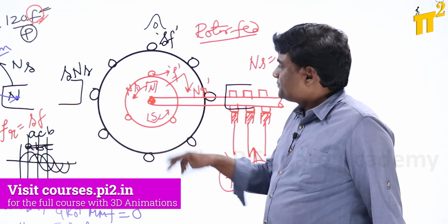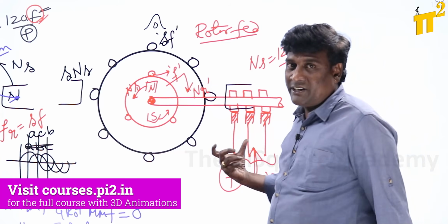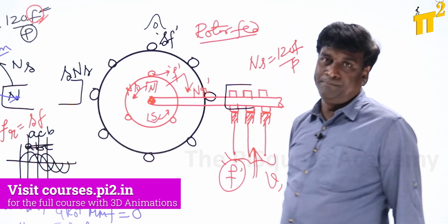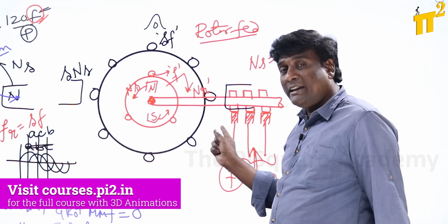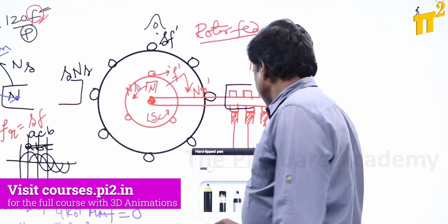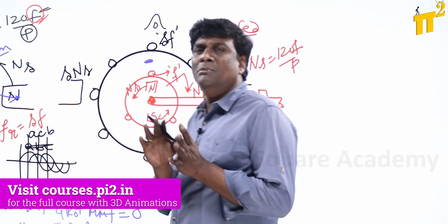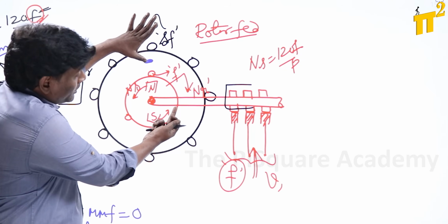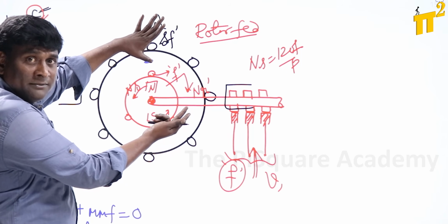Now, my rotor MMF, with constant frequency, with respect to the rotor is rotating in the anti-clockwise direction at 3000 rpm. My rotor is rotating in the clockwise direction at 2700 rpm. If you sit in space, in the air gap, I'm not discussing much of the analysis part, my rotor MMF with respect to the rotor is rotating in this direction at 3000 and the rotor is rotating in this direction at 2700.